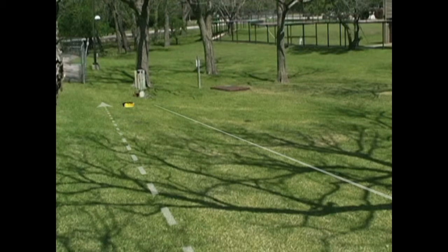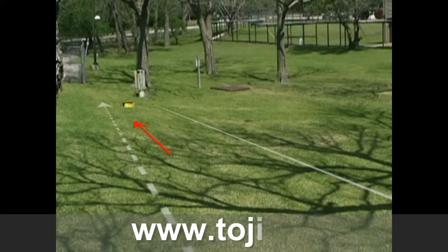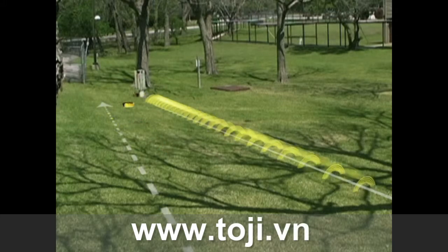When you are tracing a buried utility, the transmitter sends a signal through the target conductor. The far end of the target conductor is connected to the ground, or grounding point. The signal then returns through the dirt, back to the ground rod, and the black lead of the transmitter. The signal creates an electromagnetic field around the target conductor. The receiver detects this field, allowing you to trace the path of the conductor. All locating signals use the soil for the return path of the locating circuit.